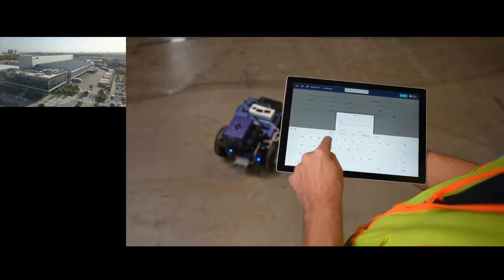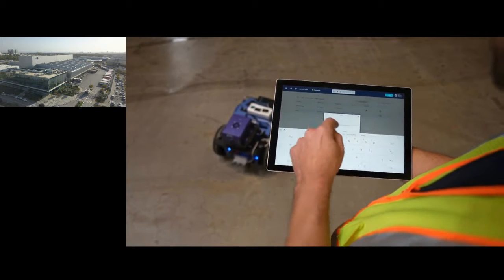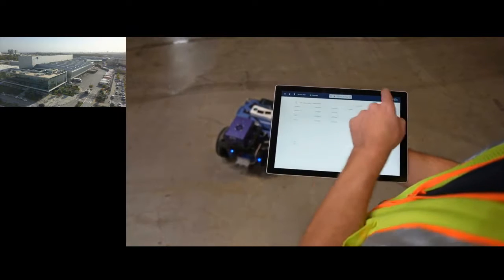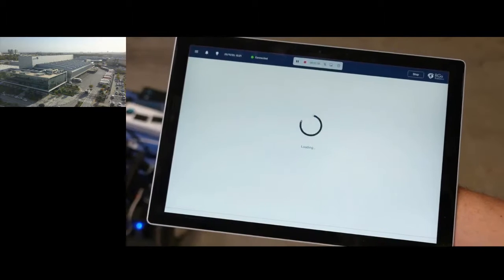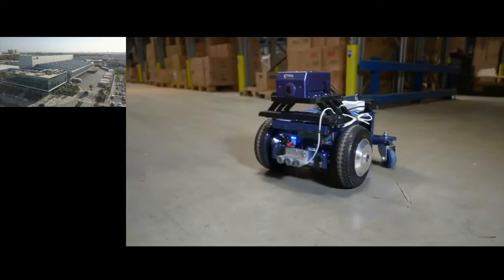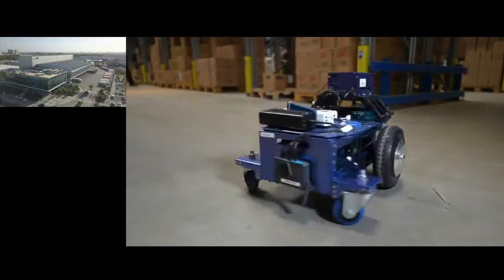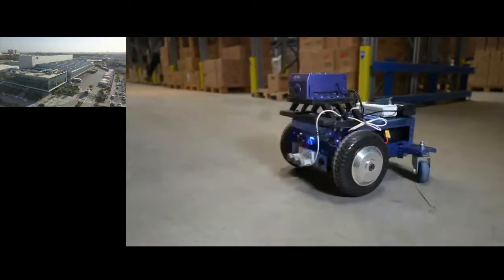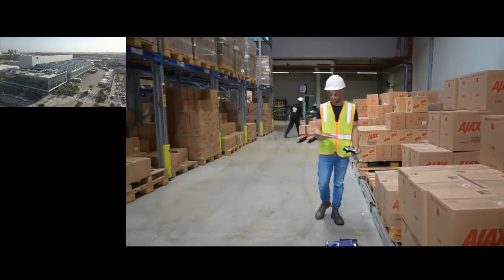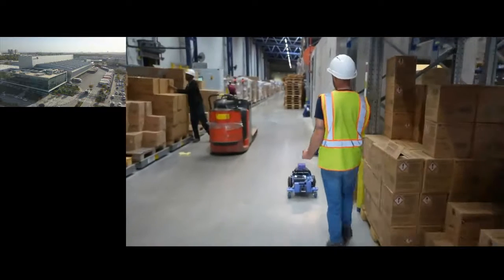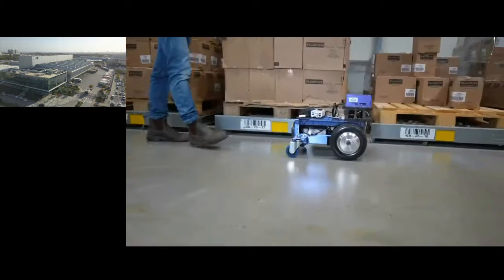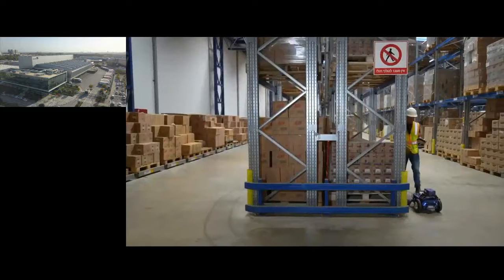And here you can see the easy go operation with our tablets and the UI. The operator just needs to create a new map, enter some info like area, size, and name, and start the perception engine. The next step, the perception engine requires a basic out-of-the-box calibration, which is done once per site. It will spin around basically for the IMU to measure itself and give you very accurate performance before you go. As you can see, the mapping process is relatively easy, just driving around using a joystick, manually driven around the warehouse.